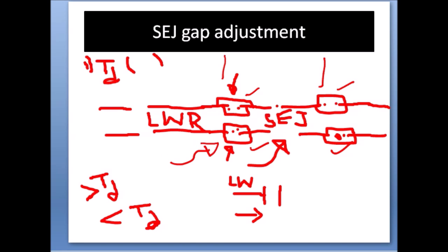we should ensure that whatever position of the tongue rail is there, it is correct. So how do you know whether it is correct or not? At TD, the tongue rail should exactly coincide with the mean position, the center line.